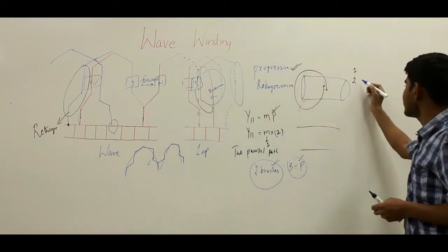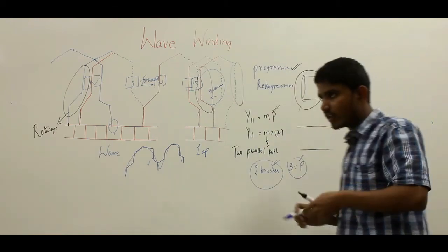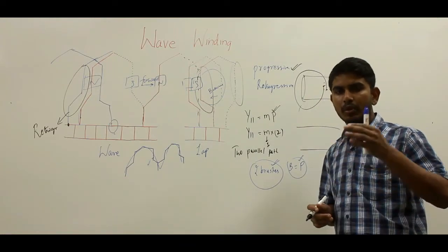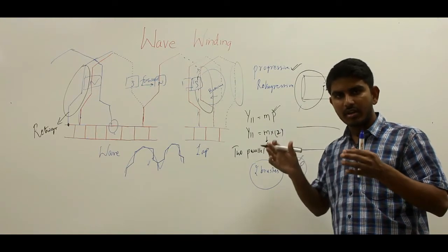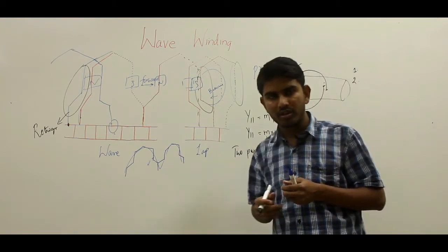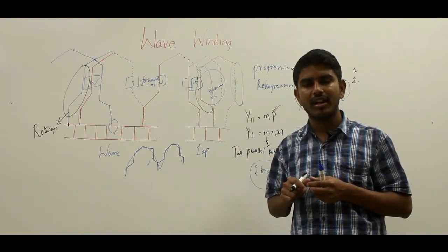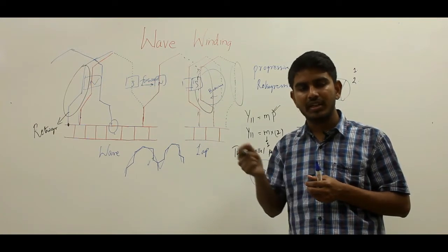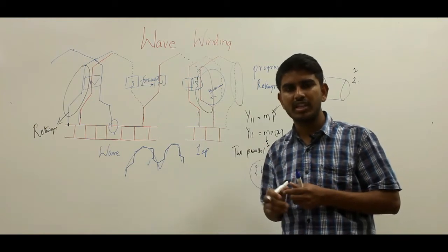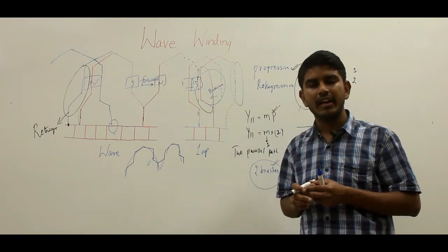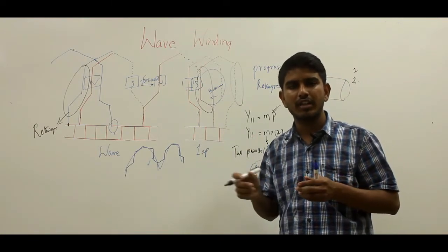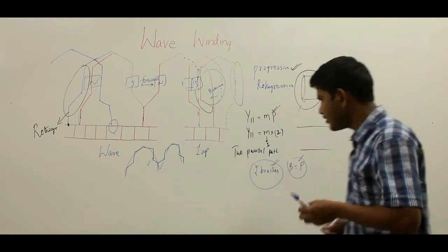Now the second advantage is, in the lap winding we have seen that there is a need for the equalizer connection, because the potential in several paths will be different. We have talked about it. One reason is the variation in the gap length, the other reason is the magnetic steel property, and the other reason is that the resistance of each path may not be the same. Because of those reasons, we have different potentials in different parallel paths, and therefore we have circulating currents. But here,